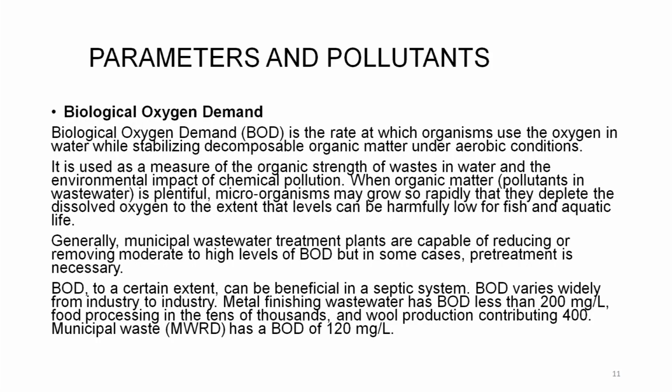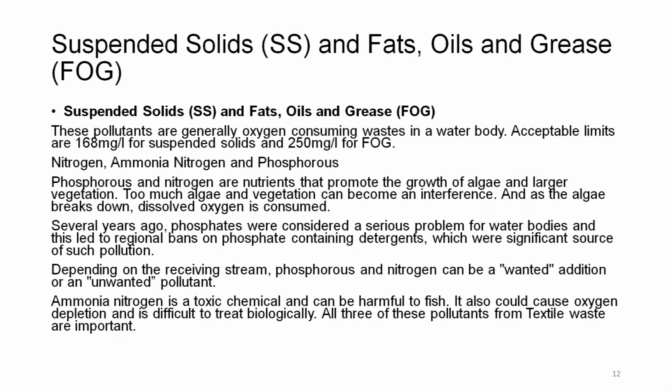Metal finishing wastewater has BOD less than 200 milligram per liter, whereas food processing is in the tens of thousands and wool production contributes 400. Municipal waste itself has a BOD of 120 milligram per liter. So, it varies. Suspended solids SS and fat, oils and grease, that is FOG.